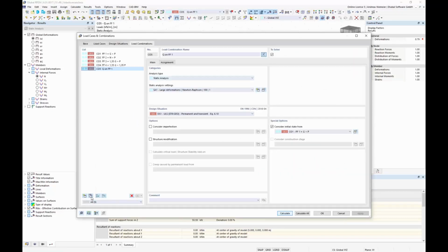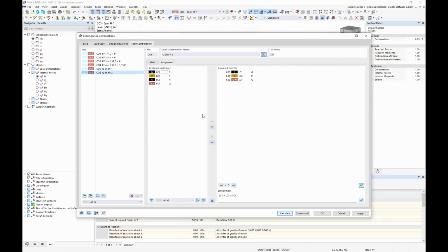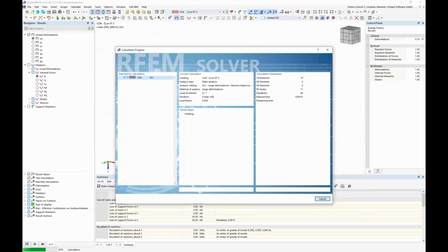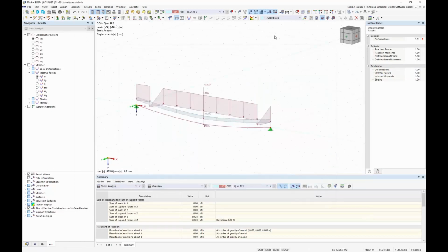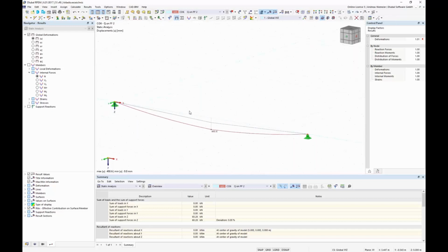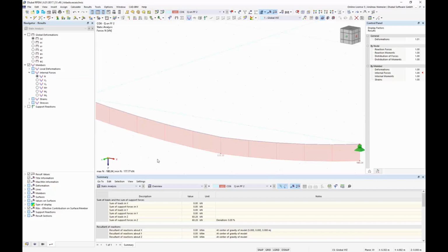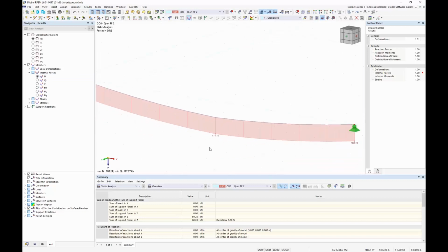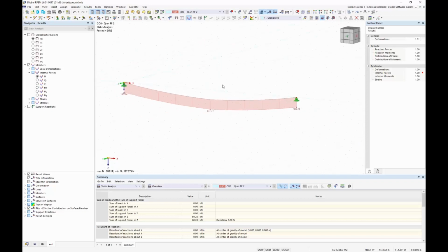and if you wish, you can also apply the same load on shape 2, which means we only change here to shape 2 and exchange the load to N. And with calculation we get the same result, only on, let's say, the original form finding shape 2 plus load is on the deformed shape with 493 millimeters with a normal axial force of 177. So this is, let's say, our new philosophy of working with form finding tasks and organizing it in the program.